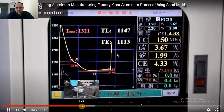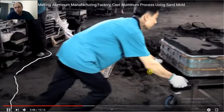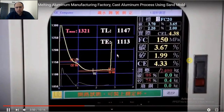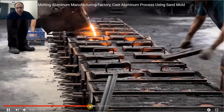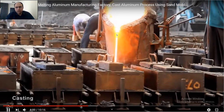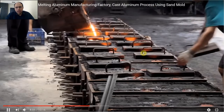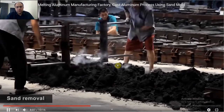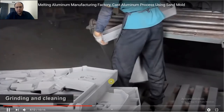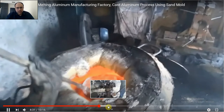Yeah, this is the mold. As you can see, this is a mold, and these are the flasks of the mold. So that's fine to get off the flasks. So all of these are different molds, and they already melt the metal and keep on pouring. So as you can see, this machine, do you see how huge it is? So he keeps on pouring the liquid into all of these molds, and these molds will be broken afterward to get the final products by casting.